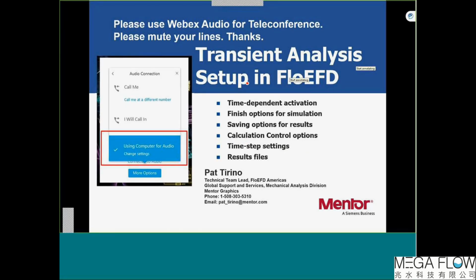What we're doing today is a transient analysis setup in FloEFD. Some of the key items we're going to cover are how to activate the time dependency in FloEFD, how to set up the finish options for the simulation, obviously as a transient versus, let's say, a steady state, and the saving options for the results in a transient. There's a reason why you're doing this.